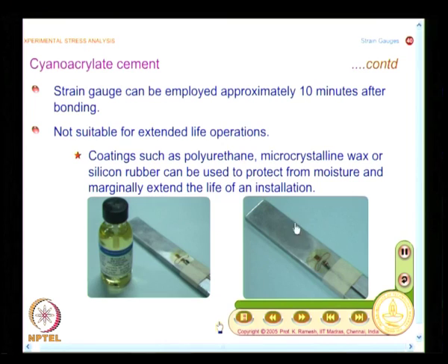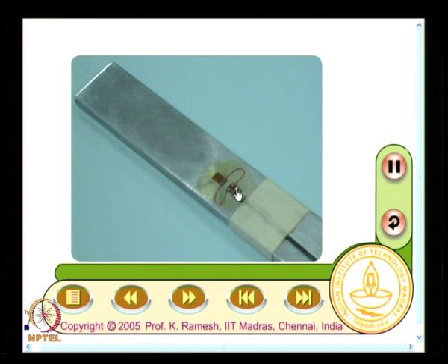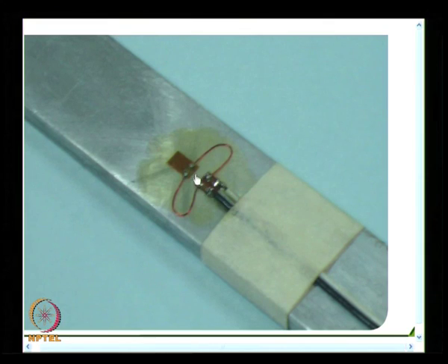And what you see here, the example is also good. You have a nice strain gauge installation, where I have a strain gauge. These are connected by a thin special type of wire, and these are all the connectors. It is easy for soldering, and this is the lead wire, and the lead wire is also anchored. So, if you pull the lead wire, that load will be taken care of by this anchoring, and it will not be sensed by the soldering contacts.